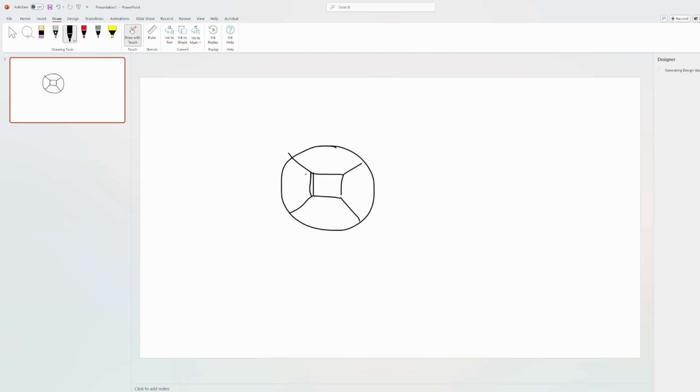And after that, we will divide the domain in each region, sub-region, whatever you call, by giving the number of mesh points in each edge.